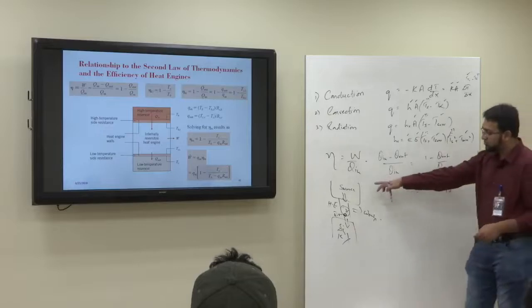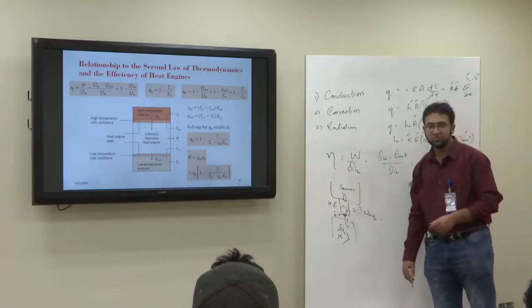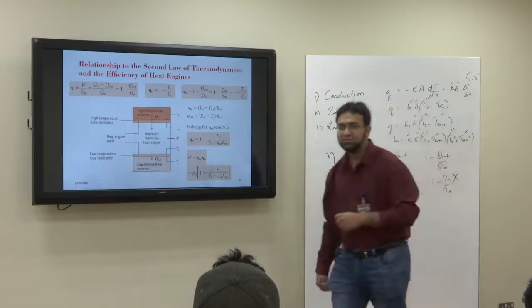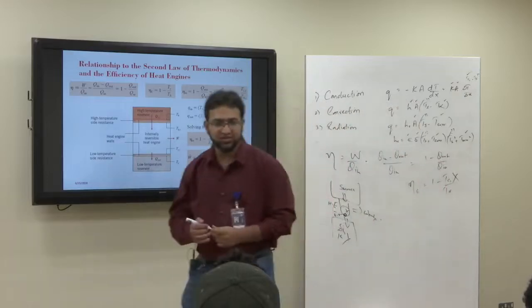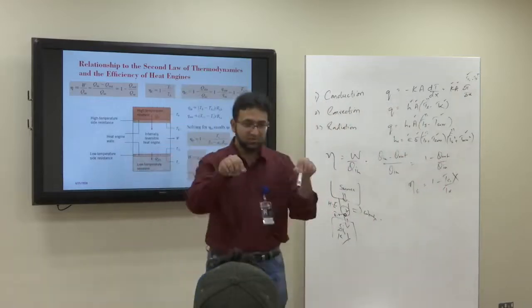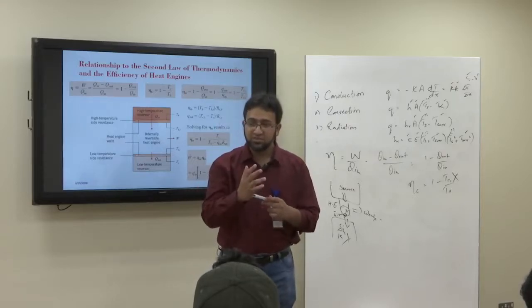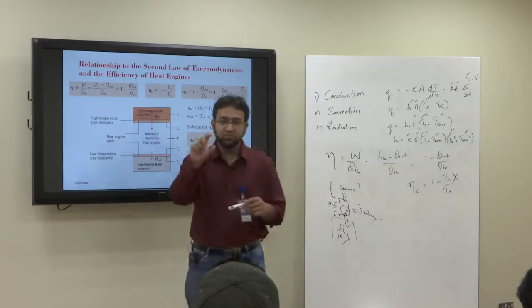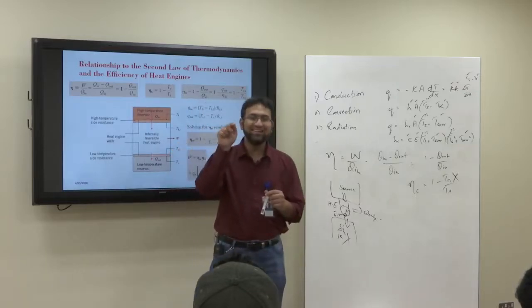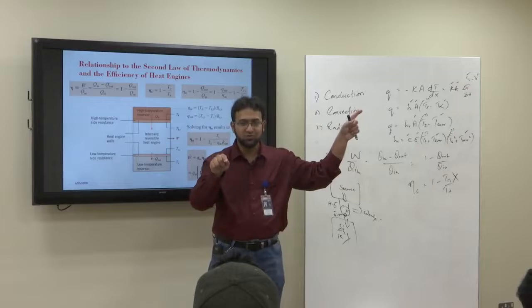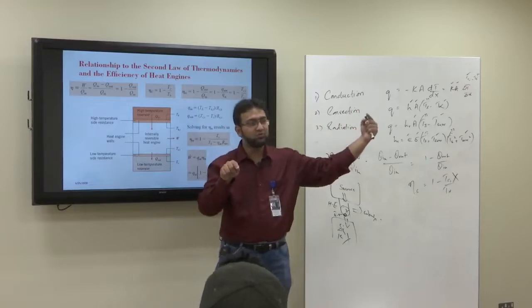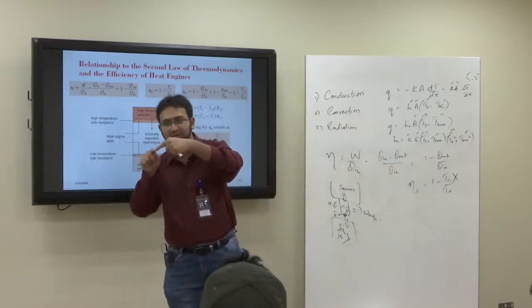A similar case is here. You have the source supplying heat to the heat engine, right? If the source is supplying heat at 200 degrees centigrade, within our Rankine cycle or whatever cycle we are using, the temperature of the boiler should be slightly less than the temperature of the source. We want the energy from the source to go into the boiler.